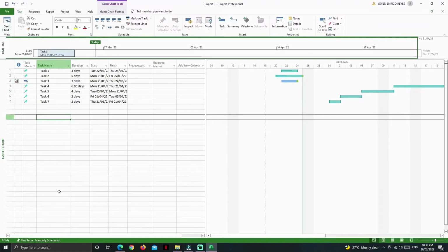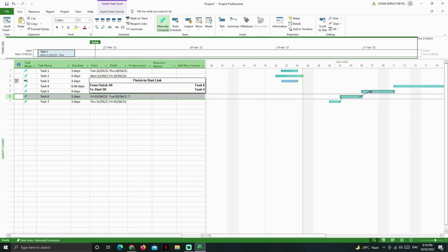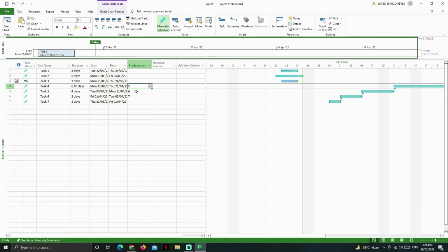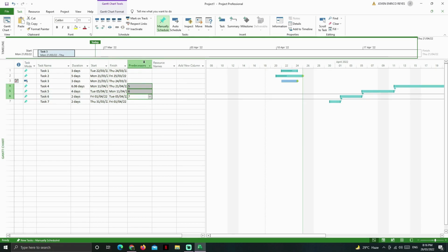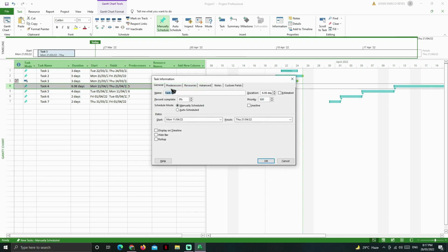You can add any dependence between two or more tasks by using links. Just drag any task vertically and connect it to another task. By default, this creates a finish-to-start link, where the second task can start just when the previous one, called the predecessor, finishes. Each task can also admit multiple predecessors. All the predecessors of any task are listed under the Predecessors column. To manage links between the task and its predecessors, you can open the task information panel under the Predecessors tab.